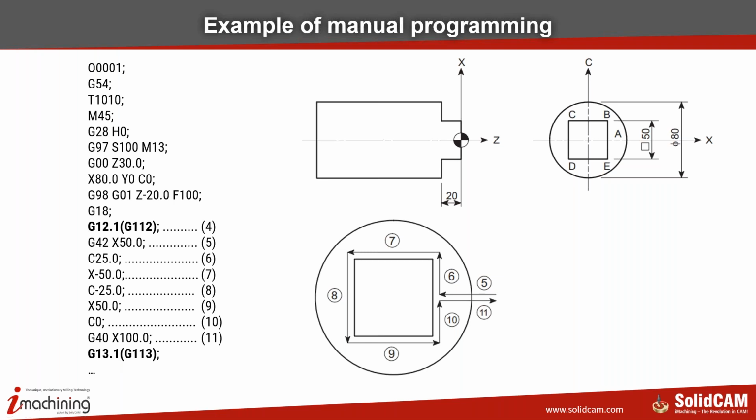A few rules here are not mentioned in this drawing. It is not possible to make G0 movements within the cycle. So G0 movements within the cycles are not allowed. So this is the first rule. The second rule that they usually state is that you must start with C0. As I said, this is not true. And I will show you an example and the advantages of this. And I will, of course, also say the disadvantages of always having it on C0.